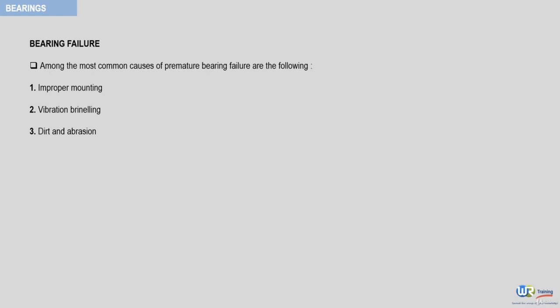Sleeve bearings on some older, slower, larger pump shafts can withstand dirt contamination better than ball and roller bearings. This is because the tolerances are not so strict with sleeve bearings. The surface area of contact is greater, and the lubricant flushing action is better. The sleeve bearing material of construction is normally softer than the shaft material, and abrasives can be embedded into the bearing material without destroying it. This is certainly not the case with precision ball bearings.